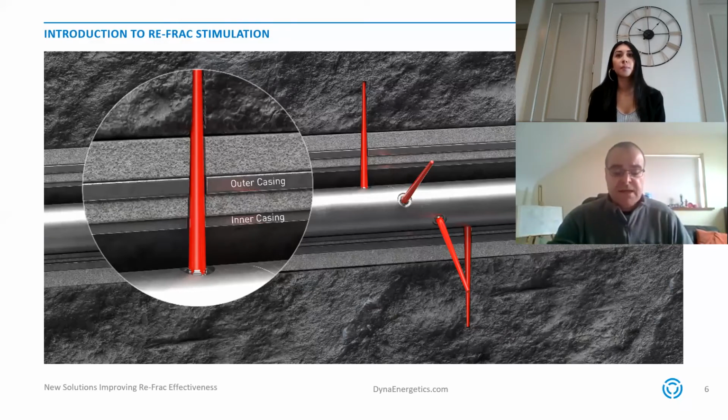Smaller guns also mean smaller entry holes in the casing itself. And again, that's usually not a problem because you can hydraulically fracture through a very small entry hole. What that usually means, though, is that perforation friction will be a lot higher, pump rates tend to be lower, the time per stage tends to increase, and the results can fluctuate greatly.